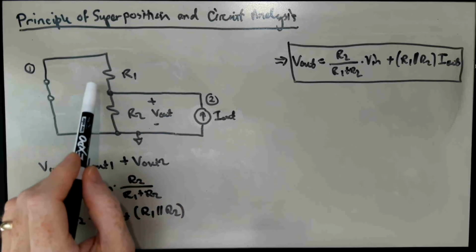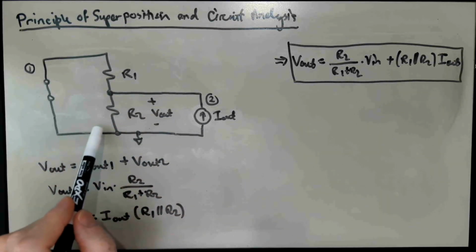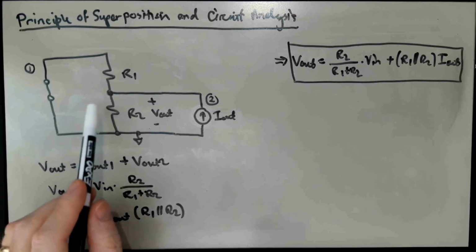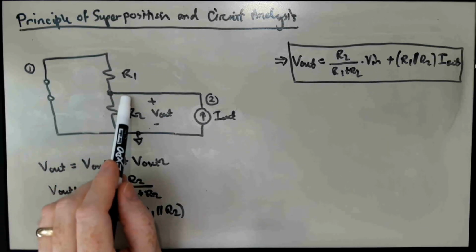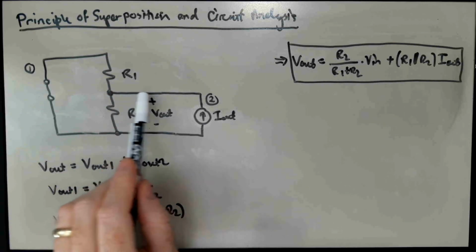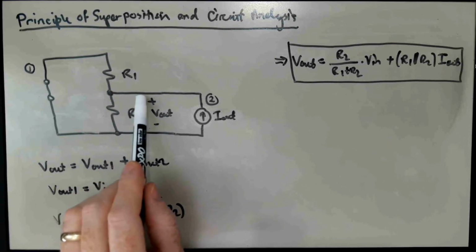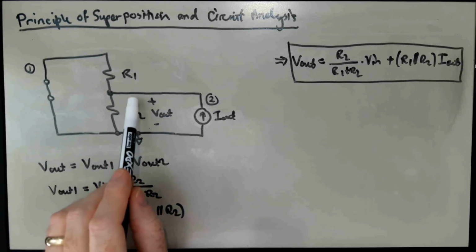Actually making a power supply that can supply current out of a resistive voltage divider is quite wasteful, because we have to use such low resistors in our voltage divider that we burn a lot of power to make this intermediate voltage stiff enough to withstand taking or putting in some reasonable amount of current.